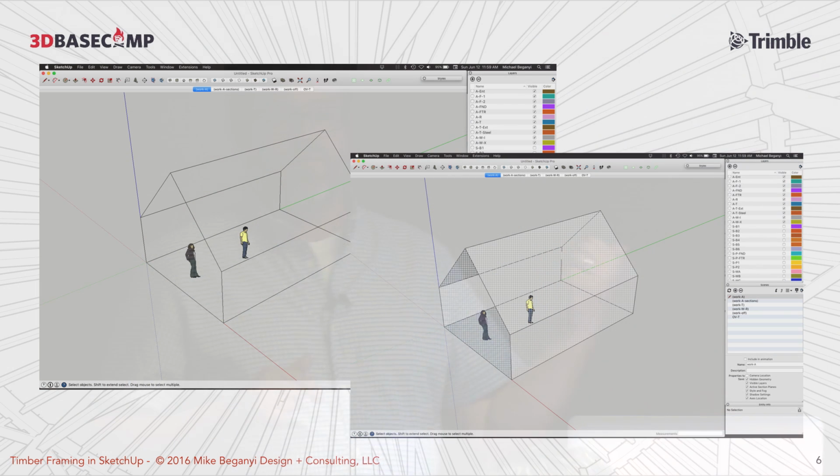A lot of times that's not what houses look like these days. They're not these simple little frames, right? They gable on gable and roof on roof, and they're sprawling sort of monstrosities. So a lot of times if it's not a simple frame, I'll actually build a shell out of surfaces and lines, and I'll create a wireframe model, and I'll hide the surfaces. I make it a component. That's the first rule of SketchUp, make it a component. I'll hide all the surfaces, but I'll keep that wireframe and lock it. And I use that so that I can bring other joinery, other geometry to it.